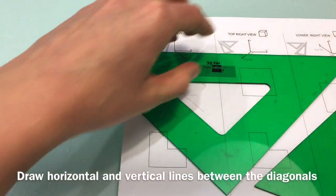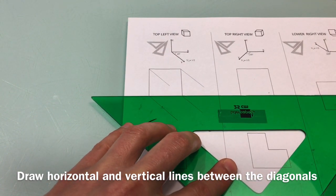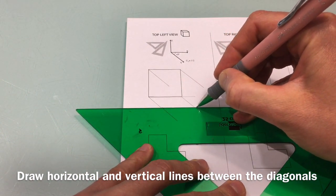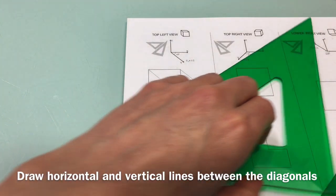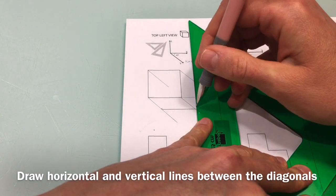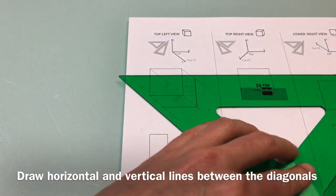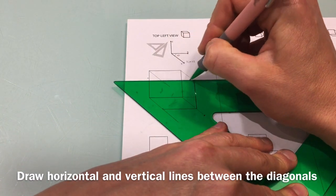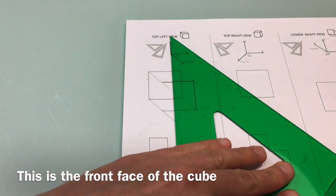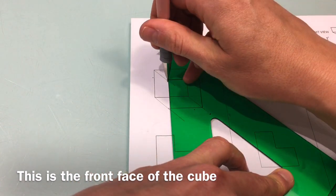I continue working with my triangular set of squares, drawing parallel lines, horizontal and vertical. Where this horizontal line meets the parallel to Y, I flip my tool to make the vertical line between these two. I rotate my tool again, and I construct the front face of my cube. Make sure the 30-60 degrees triangle never ever moves.